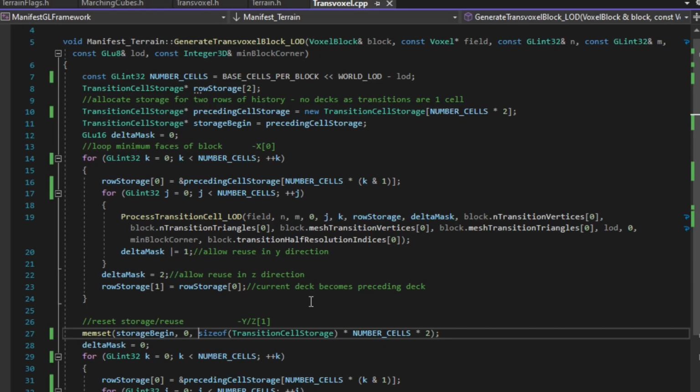For any extraction, we loop over the A-axis first, and then the B-axis with respect to the local coordinate system defined by n. Luckily, in both possibilities, B is always the K-axis, so A is whichever axis n isn't, where n is the transition face. So for the X extraction, we go over the J chords for a given K, then increment K. For a Y extraction, we go over the I and then increment K. When extracting a block face, we supply the parameters with one of the predefined indices, from 0, meaning minimum X, up until 3 for the max Y.